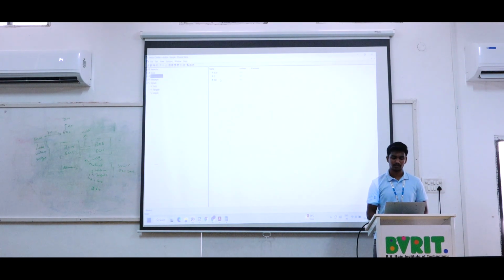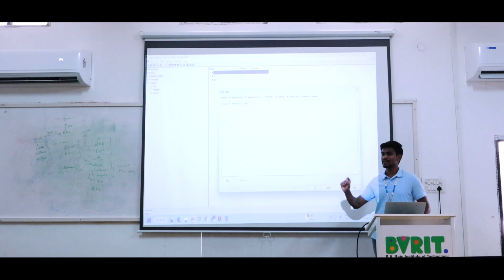Going to RK, which is a transmitter, so I can set the RK ECU and transmit the messages. Add ID number 400. Then click OK. In the same way, we are going to set the BCM, body control module, as a receiver. So going to check the body control module, map it as an RX signal. Don't confuse it. Transmit means you are going for the TX messages. You are not able to send an individual signal. You need to transmit as an identifier 400.